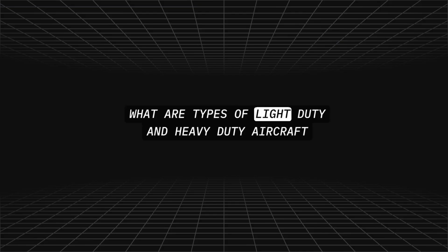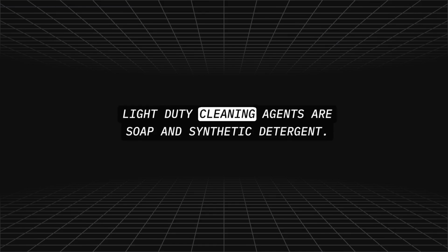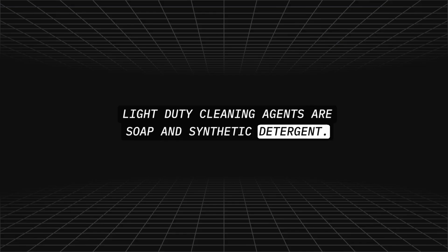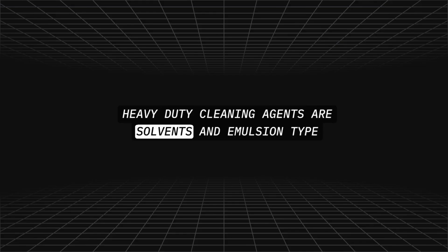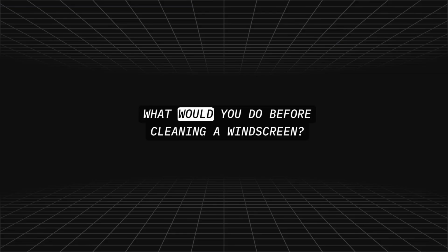What are types of light-duty and heavy-duty aircraft cleaning agents? Light-duty cleaning agents are soap and synthetic detergent. Heavy-duty cleaning agents are solvents and emulsion-type cleaners. What would you do before cleaning a windscreen?